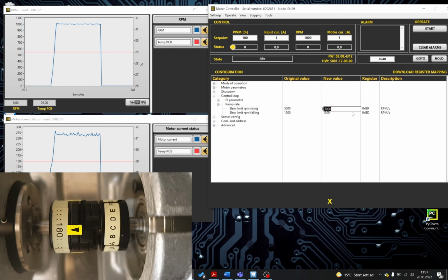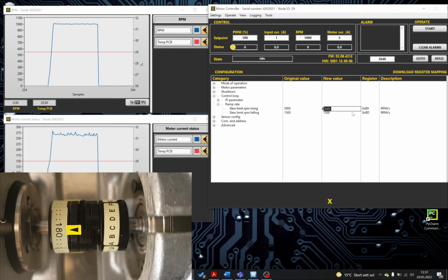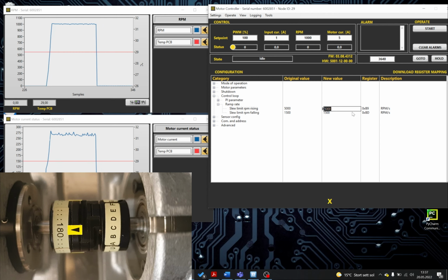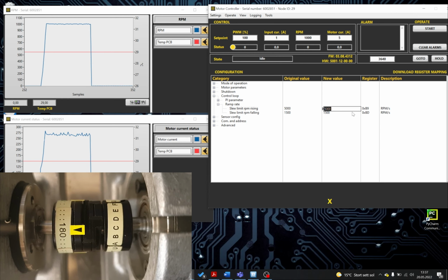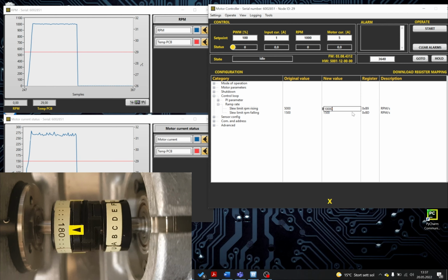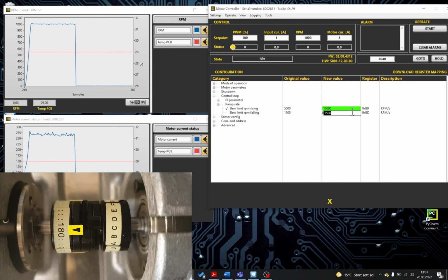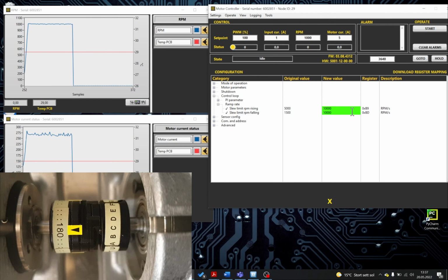In many applications, you don't want the motor to spin up quickly. That will usually make it draw lots of current. But in some maybe lighter applications, you want it to spin quickly, and this is what I want for this setup. For other setups, you can use this limitation to provide desired acceleration. But okay, right now I'm going to put this to 10,000, and also the acceleration to 10,000. So it means that it allows the controller to go from 0 to 10,000 RPM in 1 second.